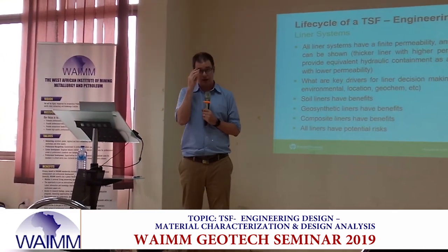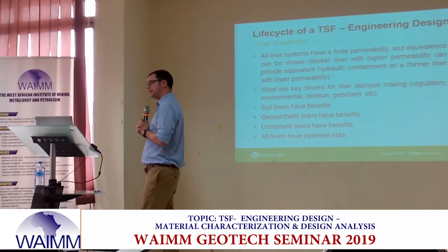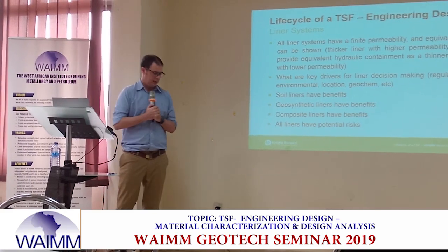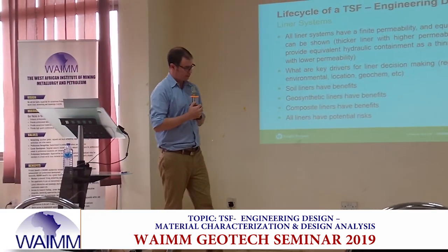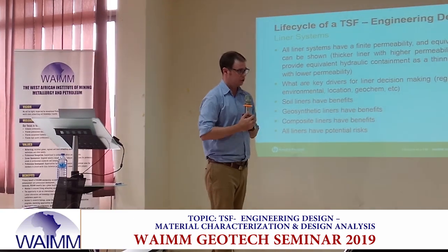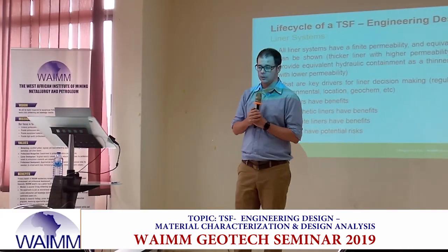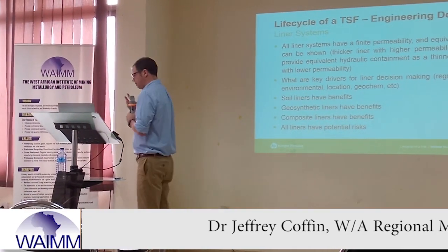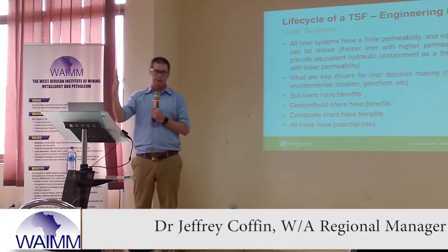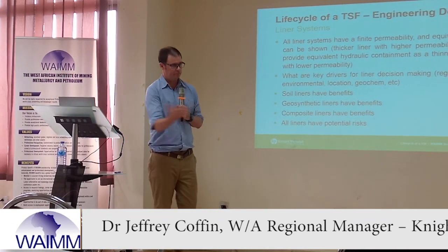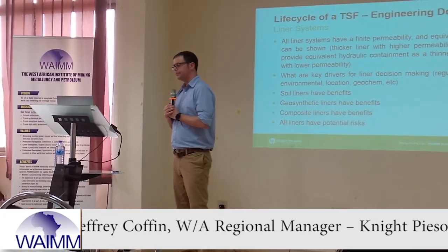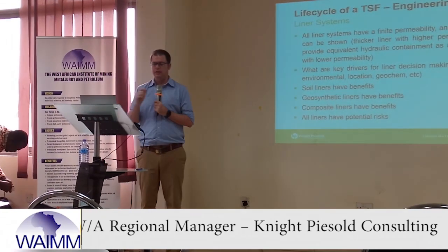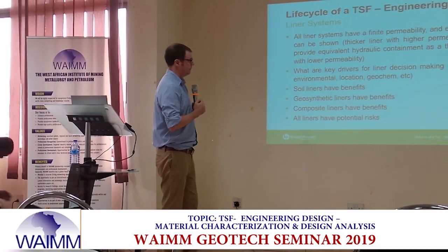Obviously, this has been an interestingly debated discussion here in Ghana for a long time. And most recently, the discussion of compacted soil versus a geosynthetic material for hydraulic barrier. And we're not going to debate which one is right, which one is wrong. We're just going to talk about the facts, just the facts. Okay? The number one fact that we need to consider here, guys, is that all liner systems have a finite permeability. Okay?